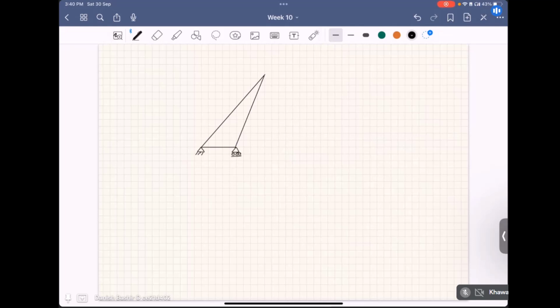So here there will be no external loading, and we have to compute the deflection in the horizontal direction. We will apply a 1 kilopound load in this direction. Okay. Other things are already known, that this is 4 feet, this is 5 feet and 12 feet. I will not write it again.